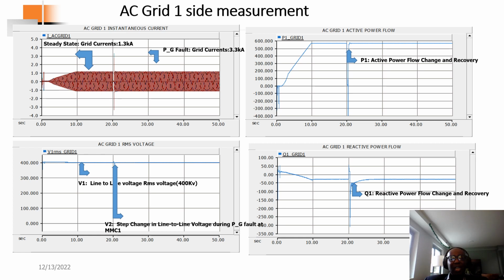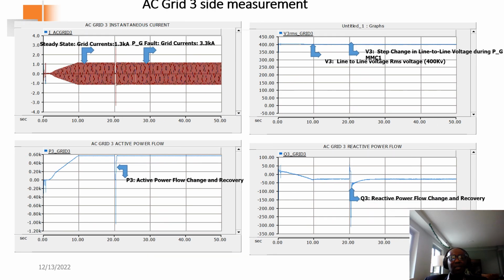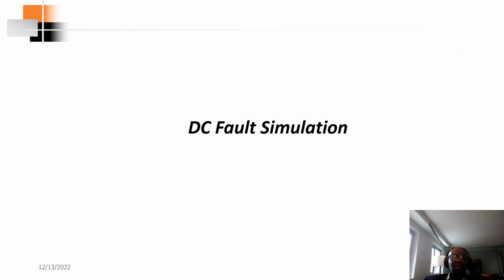So we look at the time that the AC side circuit breaker was able to recover from the fault. That was about 40 milliseconds, and that is a lot for these MMC converters, and that's not ideal for the power electronics. And that itself can cause a lot of chaos and basically collapse of the HVDC grid. So it requires an intervention, and the intervention means that we need a DC circuit breaker, a hybrid circuit breaker, to implement the required selective fault clearing strategy.